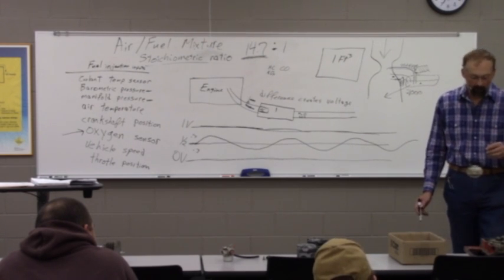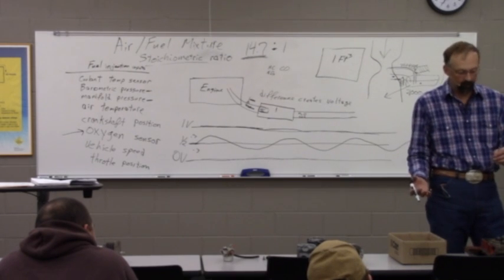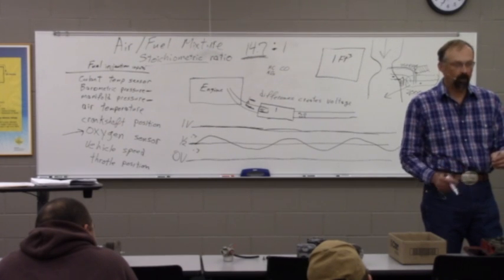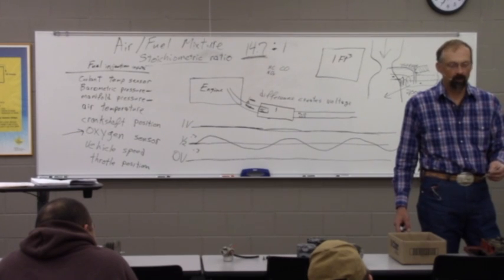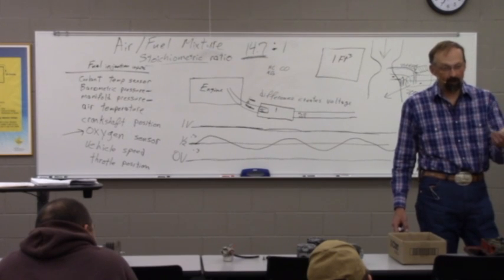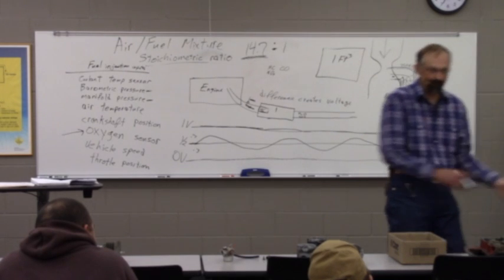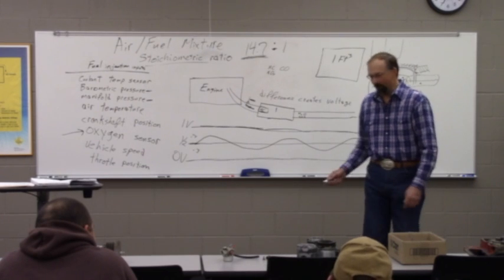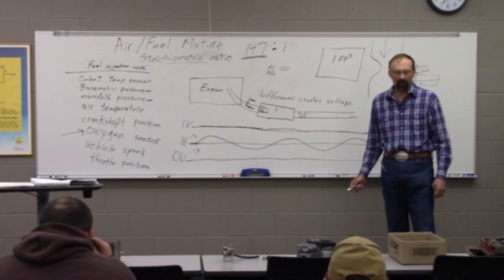Because what would happen if vehicles that were designed to run with leaded gasoline were run without it, it would just pound the face of this valve off, and the valves would no longer seal because they were beat to death. So whether the better metal came and allowed them to use catalytic converters, or the catalytic converters came and they had to do this, I'm not sure. They both kind of came in at the same time, more or less.